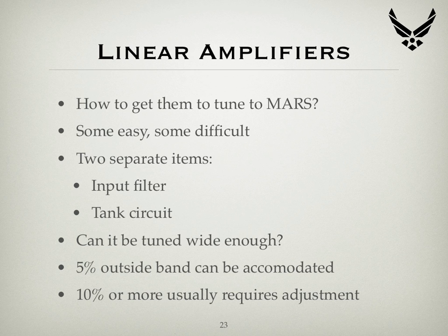Now the other item is the tank circuit, that is the circuit that's on the main antenna side of the power amplifier, that is basically used to filter out unneeded frequencies and give reasonable tuning, and usually the Q on most tank circuits is about 13, 14, and there are some variations but not much.